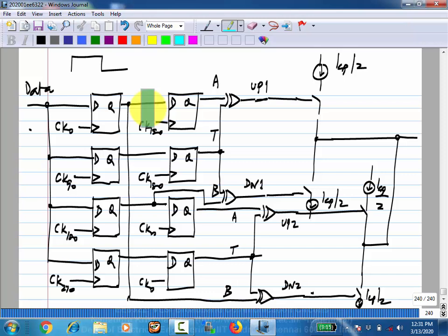So at that point, essentially, if you plot the power consumption versus speed, it goes linearly and then it starts going up like that. But if you are somewhere over here, it makes sense to come to half the rate, because then the power savings will be more than half, although you have twice as many flip-flops. Okay? This is fine. So this is the motivation for half rate, and sometimes you even go to quarter rate. Okay? This is still a sort of analog implementation, right? We still have these charge pumps, but we are kind of using every waveform here. These waveforms will have twice as much period as the single period, so it will have better settling behavior and things like that. Okay.